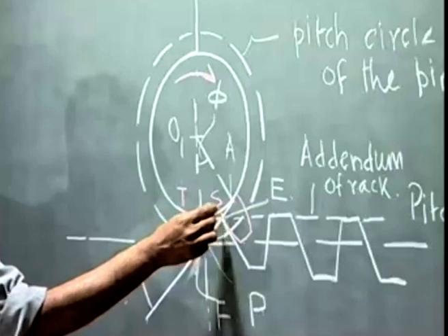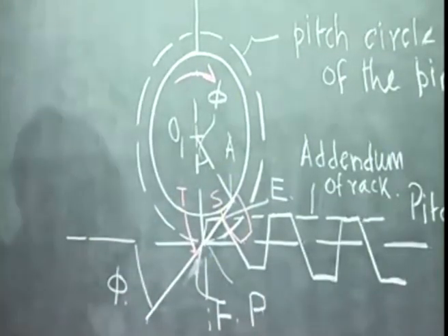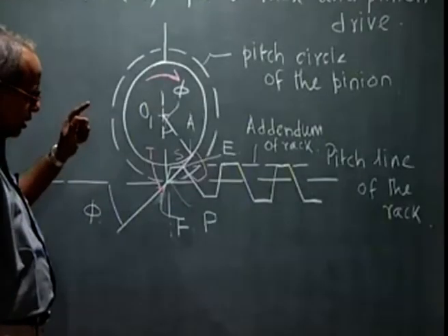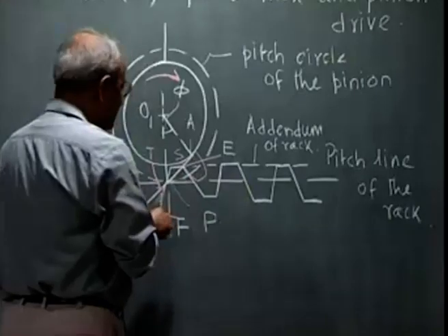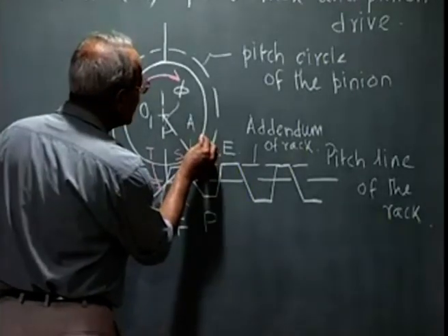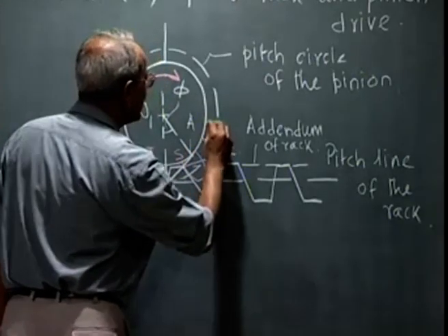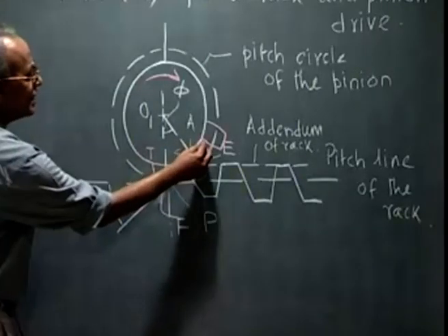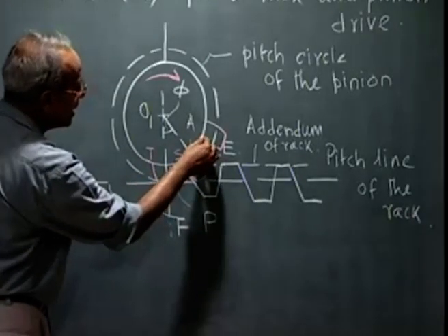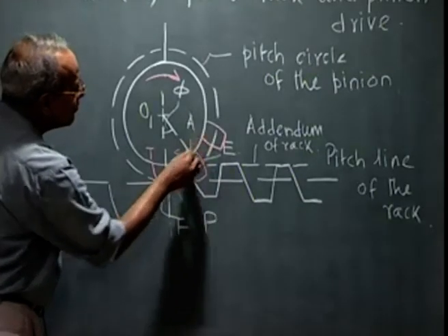This point S of this tooth has moved up to this point T. Now to ensure that the teeth remain in contact, the adjacent tooth on this gear must get beyond this point.